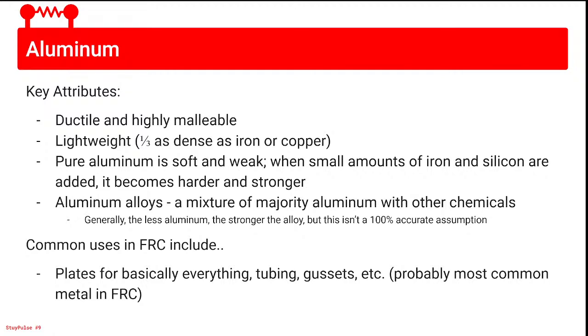So once you put a little more torque on them, they're likely to bend. That cost us a lot of time and effort; we had to spend half a day to a day at the championships this past year just replacing all of our shafts because of that. So take note of that. REV Robotics lists it on their parts, but you want to use 7075 wherever possible.